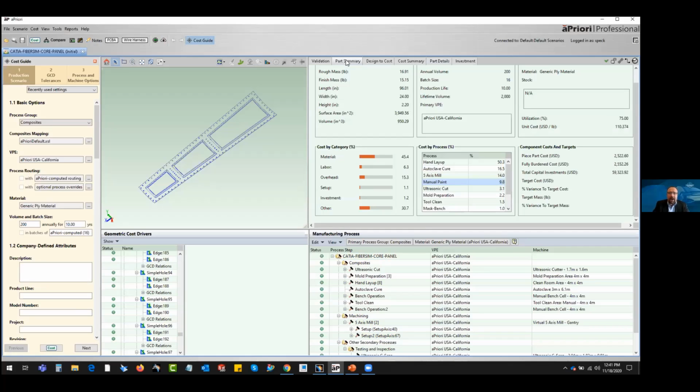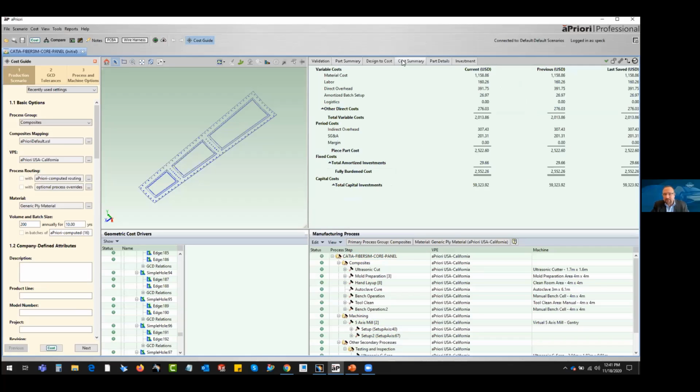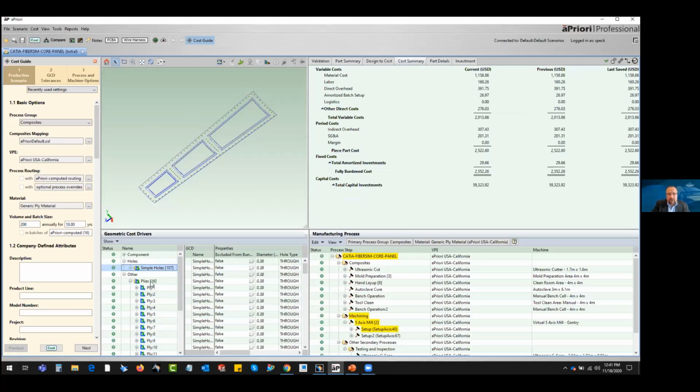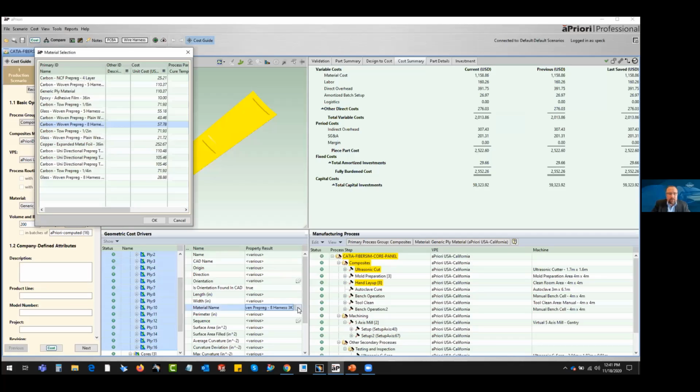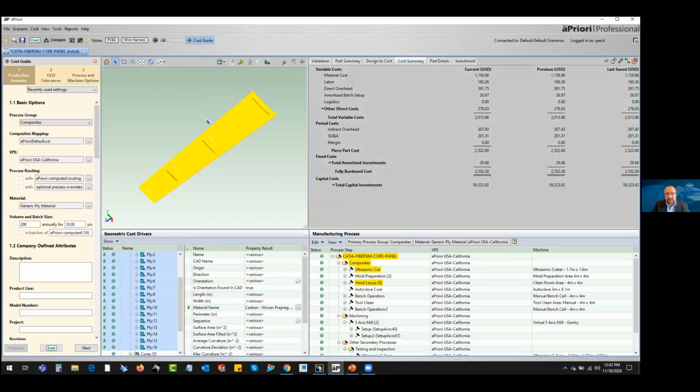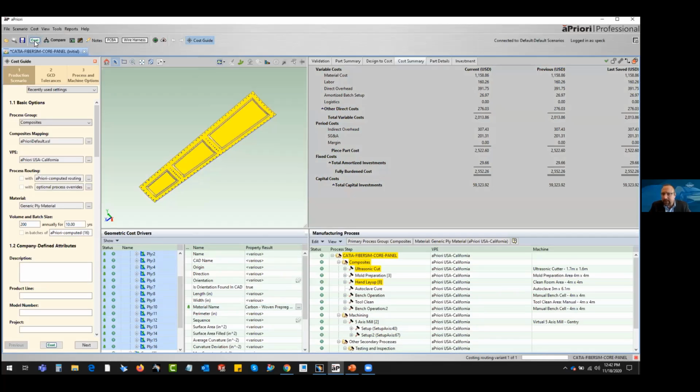And perhaps as a designer, let's assume that this part had a target, for example, of $2,000. We're over by $500 on this. So what could we do? Well, we got that view that material was a 45% contributor. Perhaps there's an alternate material, it's a piece of secondary structure. Stress is okay with a material change as long as we don't change the ply count. But right now we're using an 8 harness woven material. Perhaps we use a plain weave material that's a little more cost effective. What would the impact be? How much impact would that really be?